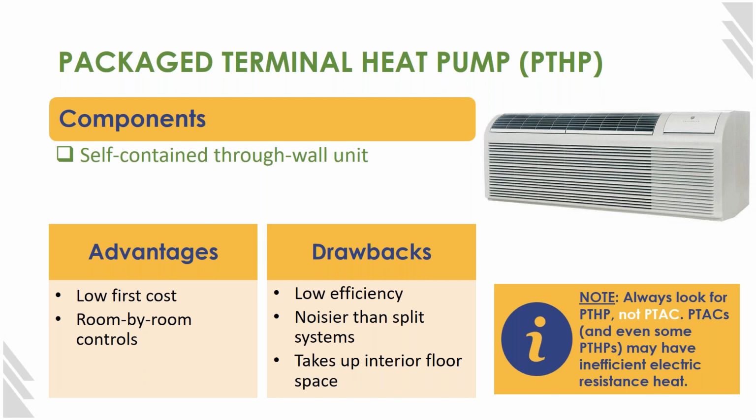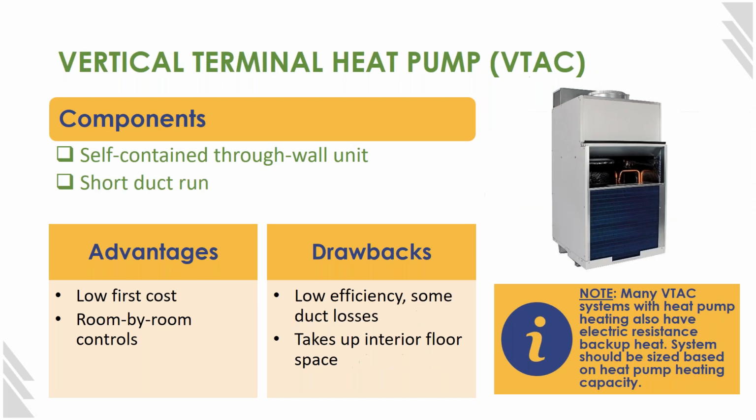I've seen cut sheets that can be very confusing where you think, oh, we got the heat pump. And it's like, whoop, little electric resistance heater built in. And you have an option to not do that. And you just have to be careful. So that's package terminal heat pumps, or PTHPs. They're very low first cost. So we do see these in quite a few projects for cost reasons specifically.